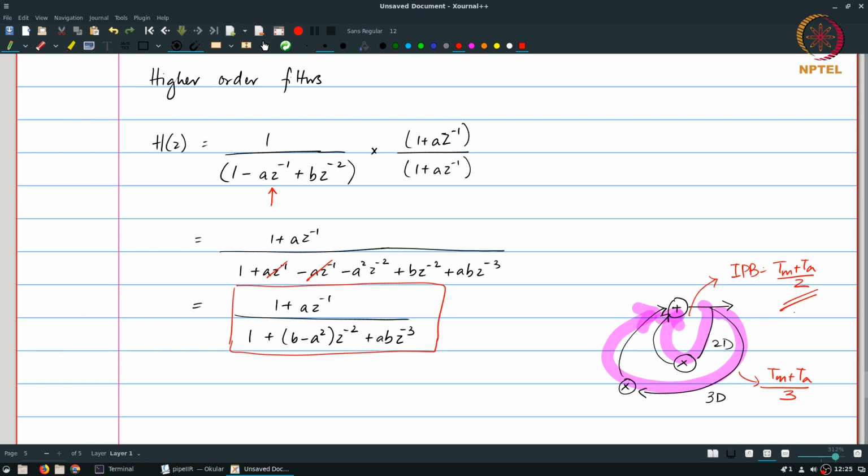On the other hand, what we can see is that if we have further domain knowledge, in other words, when we know that we are actually doing mathematical multiplications and additions, as in the case of the IIR filter, we can use certain properties of those particular mathematical operations in order to change the algorithm that is being implemented. The resulting algorithm, in certain cases, if we have done it right, can have a lower iteration period bound and therefore a lower sample interval than the original structure that we started with.